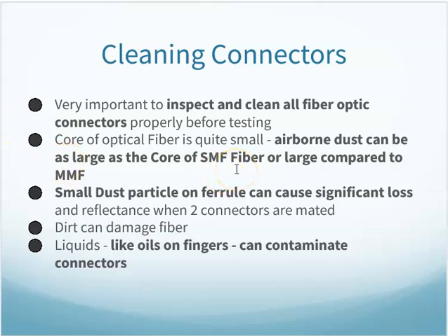Airborne dust can be as large as the core of the fiber. Dust particles can cause significant loss. Sometimes if the dirt is, I'm going to call it like sandy or something, it might actually scrape or damage the fiber. And oils from your finger can contaminate the connectors as well.